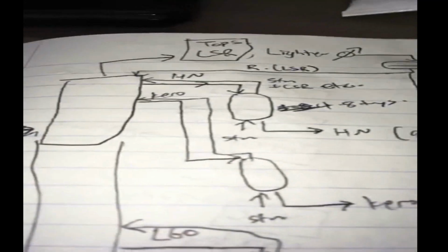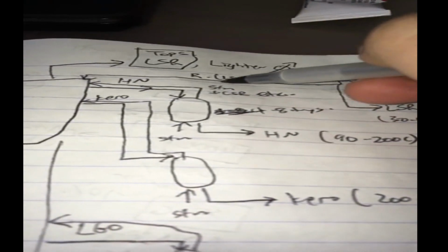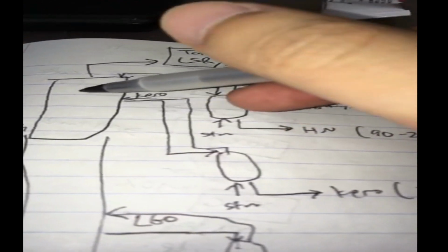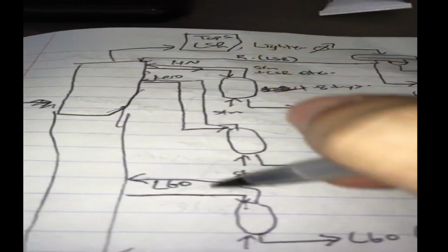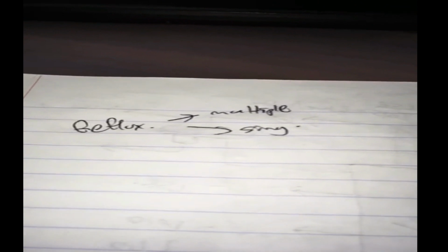Now, the last problem we want to tackle is our reflux. So do we want multiple sources of reflux or single? That means everything comes out at the top. Single reflux means if I look at our tower, the only reflux I have is from this light straight run gasoline. Everything is going to pour back here, and that is supposed to cascade down and cause the cooling. So would I rather have that, or some of this heavy naphtha I put back here, kerosene I put back here, and light gas oil I put back here, something like that. Do I want multiple streams of reflux or single?